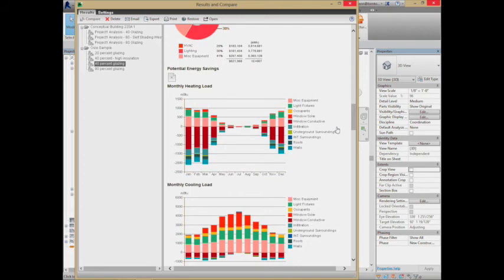In terms of the heating load, in this chart we can see a little bit about what's going on here. If I look at all the different places we're losing heat right now, probably the biggest thing is this notion of window conductive. That's how much actual energy is going right through the window surface. So if I was looking at improving this building, I might take a look at just improving the efficiency of the windows, something that has a lower U value, so it's not conducting as much heat. What would be next? Most of the rest of it's not too awfully bad.